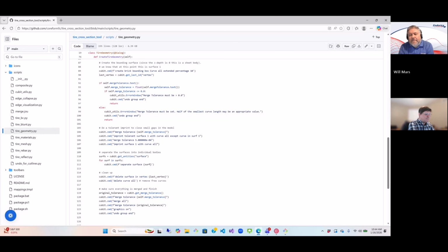The other thing that I found that's a problem occasionally is someone will give me a piece of tire tread and just trying to determine, where do I cut this? How do I cut it up so I'm not creating small rectangular slivers? Triangles are death to a hex mesher. If I have a triangle on the side where I'm sweeping from top to bottom, I can't do that. So trying to determine where to take the cuts for symmetry and getting that all taken care of, that's one of the bigger obstacles I've seen in building tire meshes with Cubit, frankly,